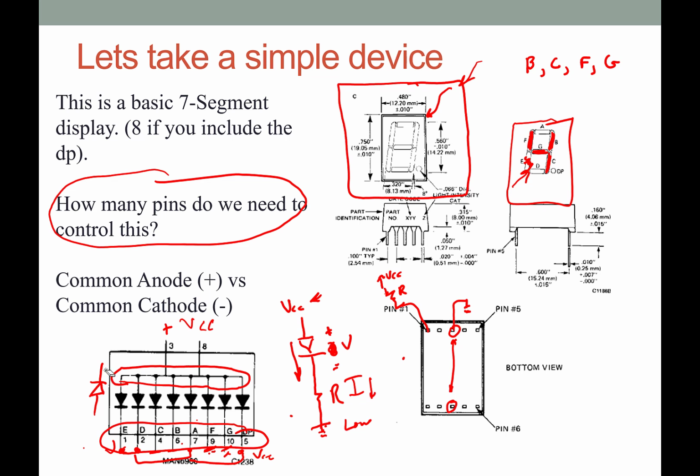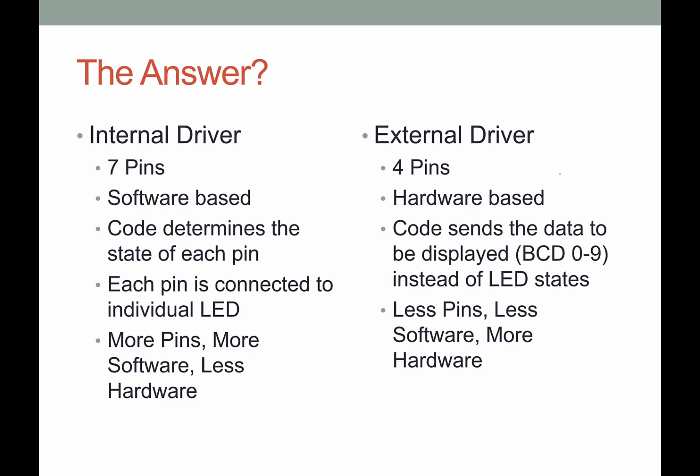And it looks like when you have this particular setup, if you think of just the standard things, for each one of the segments plus the decimal point, we need a way to display that. So there needs to be at least 8 for those. And then, of course, you might say, okay, well, maybe you need 9 because you need that common terminal because somehow ground has got to be attached. So in any case, let's think about that, and that's what this says.